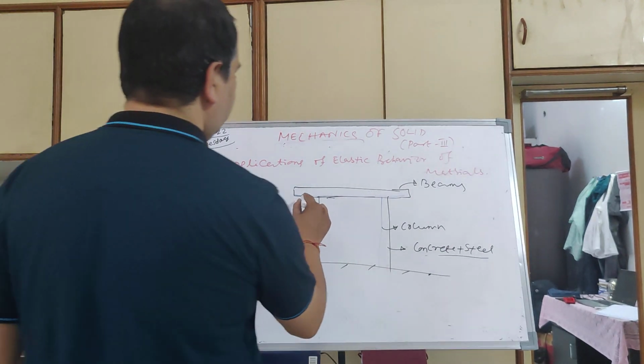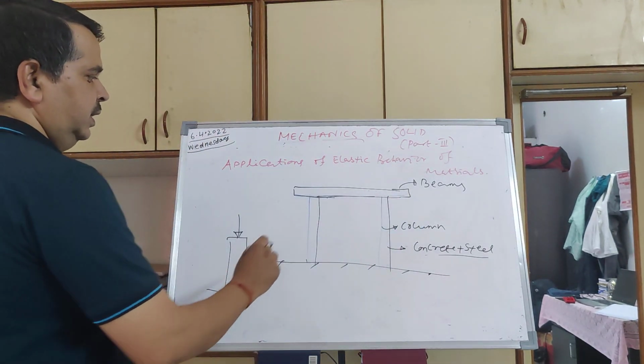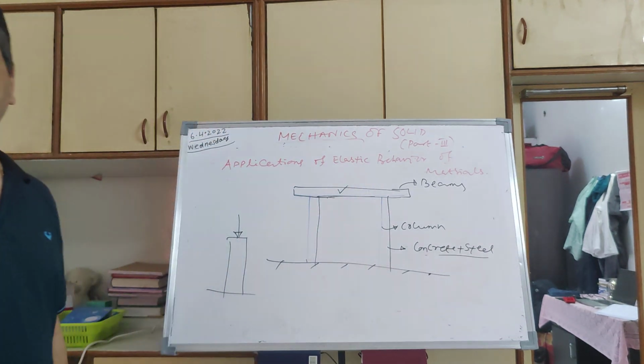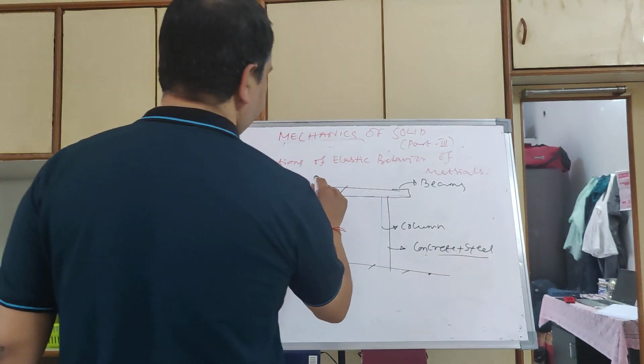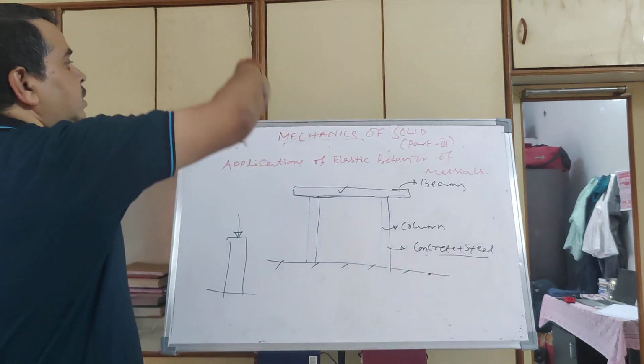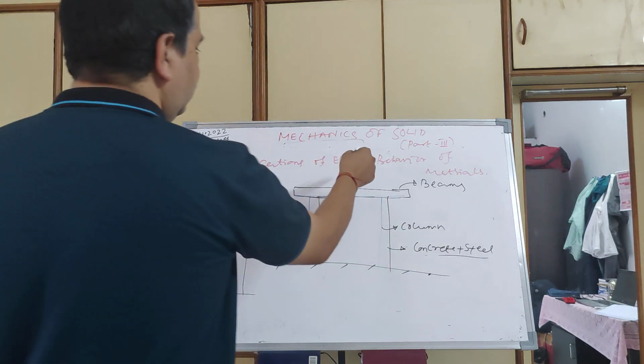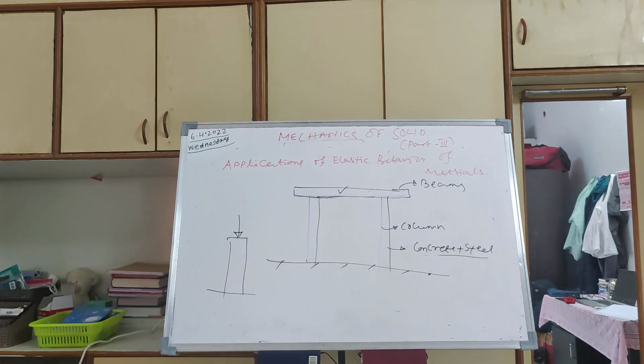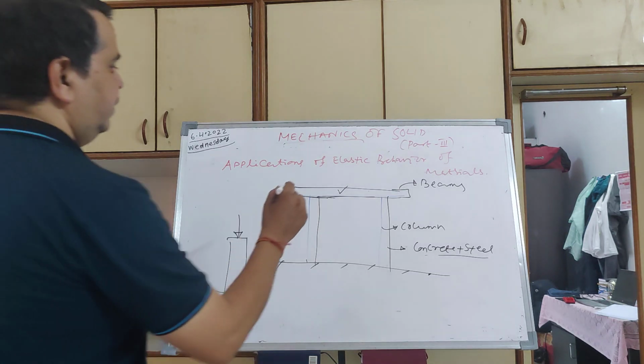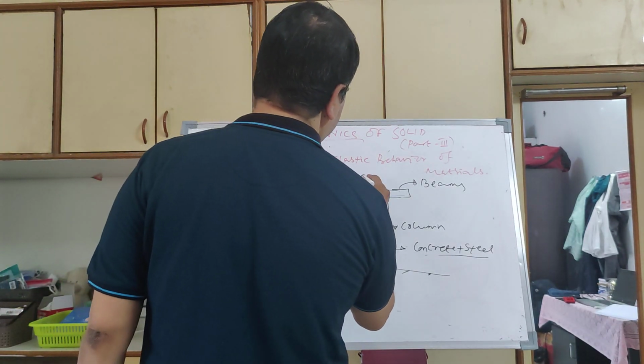What kind of weight will actually be on the building? The self weight of the roof, right? And also you will be designing for, suppose you are going to build another story on this building in future. So what kind of load is this going to carry? Let us say it is going to carry 1000 kilonewton load.